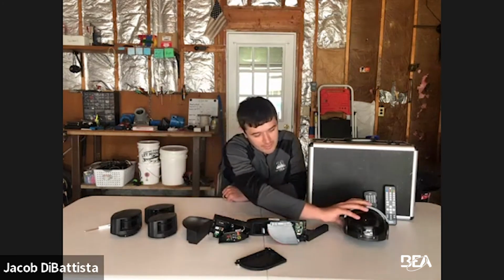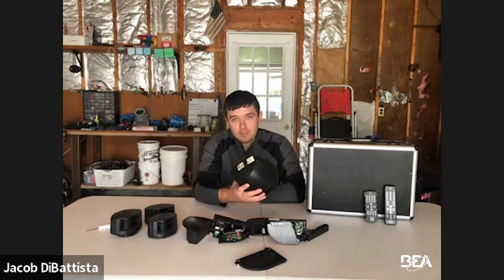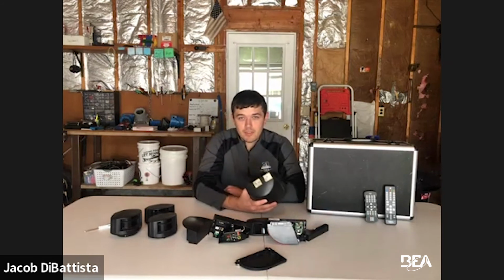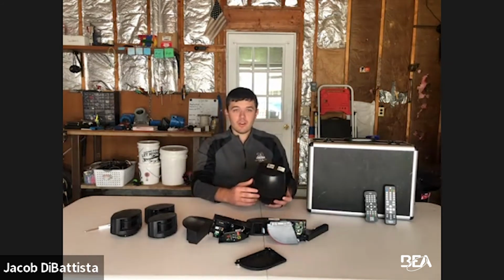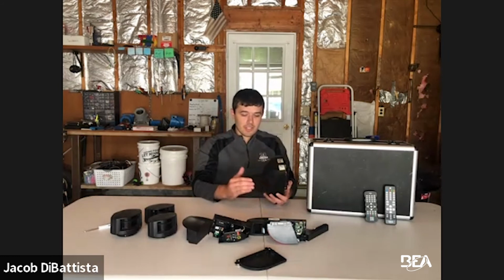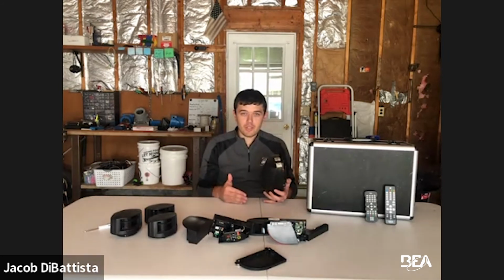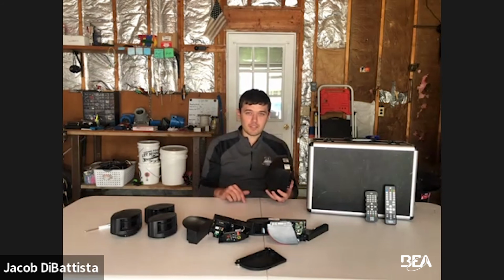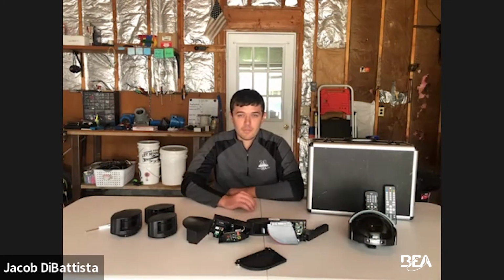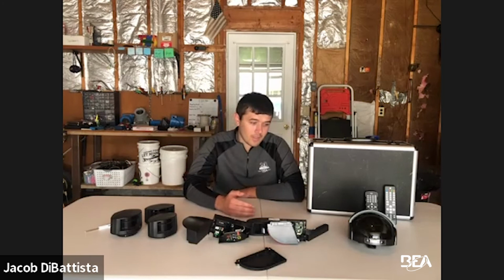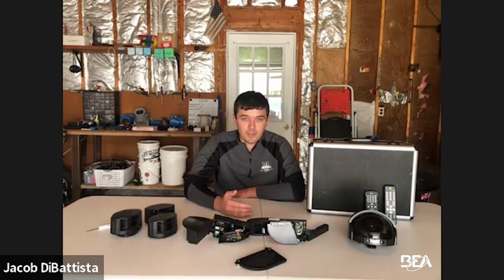The thing about the wide scan as well is it's the same concept as the i30 and the flat scan 3D in terms of a virtual push button, but it does a virtual pull cord. So if I had a garage and whenever you're standing in one select spot in the field, you want that to be what opens it, the wide scan will send the signal that only when you're in that spot on the field, it's going to send a virtual pull cord signal to the door operator and allow the door to go open. So it does both motion, presence, just like the IS-40, and safety that holds the door open.